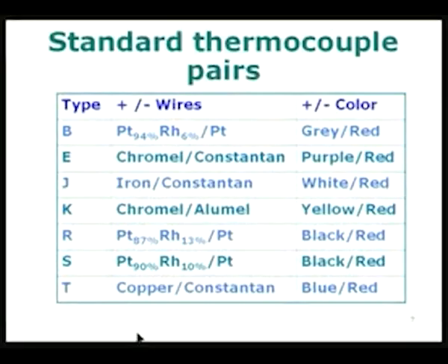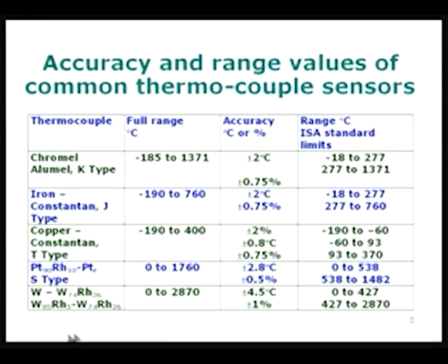And if one is using thermocouples in normal laboratory practice, practically everything can be done with the K and the T type thermocouples themselves. It is very seldom that we require the other thermocouples, excepting when the temperature levels are very high. In fact, there are other pairs which are not very standard, they are used once in a while. So I am going to look at them in the next slide.